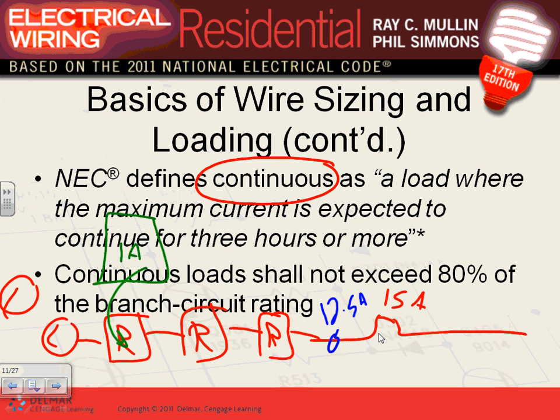All the time. I like my plasma TV running all the time. CNN is there or other things. Remember, it's only 1 amp, while this receptacle is dead, this light is off. So what's the likelihood that all these things will be plugged in and add up to 12.5 amps? That's why we consider it non-continuous.